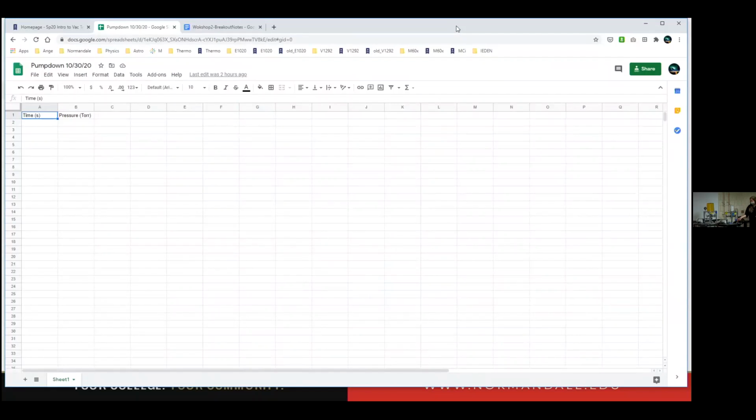And right now I've got the piezo gauge so that I can take data. And I'm going to turn on the pump, and it gets a little bit loud when I do that. And I'm going to log back in here. But you'll be able to see, you've now seen what happens when we can share things real time. So at the moment, we've actually got the system pumped down, and so I'm just going to close up the roughing valve, open up the vents, and we can watch on the different gauges on the board-on gauge.